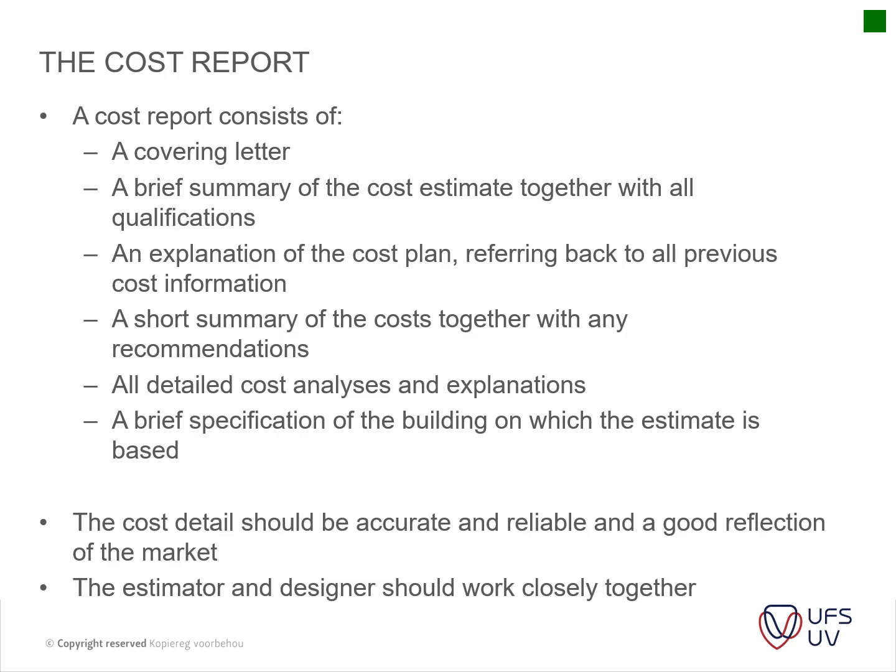And then cost reports consist of a covering letter, a brief summary of the cost estimate together with all the qualifications, an explanation of the cost plan referring back to all previous cost information, a short summary of the cost together with any recommendations, all detailed cost analysis and explanations, and a brief specification of the building on which the estimate is based.